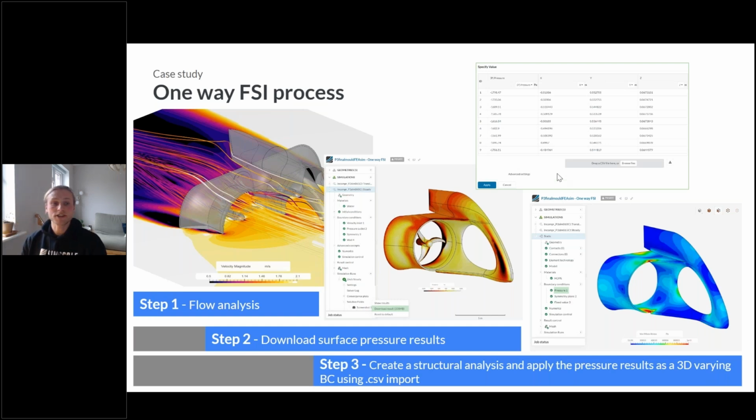So this is the first step in coupling analyses. In the future, this will all be maintained directly in SimScale, and we'll be coupling different analyses together. We'll look into two-way fluid structure interaction as well, but this is the first step in the roadmap for fluid structure interaction problems. Okay, so once you've got your pressure results in as a boundary condition, then you run your structural analysis as normal. Now, the development that we've done is enabling 3D boundary conditions for pressure to essentially accept a nodal mapping of the CFD pressure results.